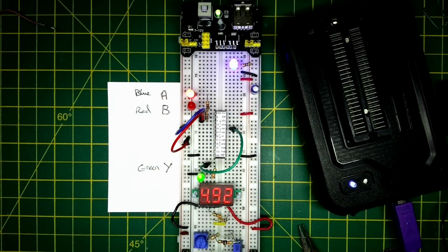So in this video, we've looked at the NAND gate, the NOR gate, the exclusive NOR gate, and we've also looked at how we can use programmable logic devices to make combinations of logic gates into a single package. So we don't need to have, say, 4 different chips to be able to have all these combinations that we've got on this chip.